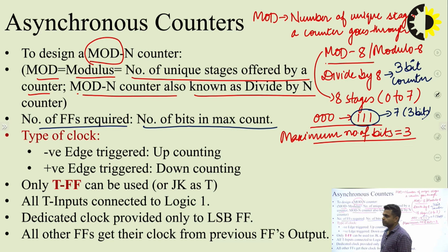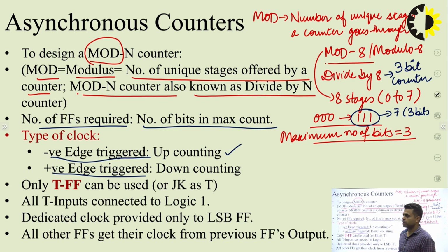Now coming to the operation of the counter, whether we want it to act like an up counter or a down counter. If I use negative edge triggered clock in the flip-flops, I can easily design an up counter. Similarly, if I use positive edge triggered flip-flops, I can easily design a down counter.